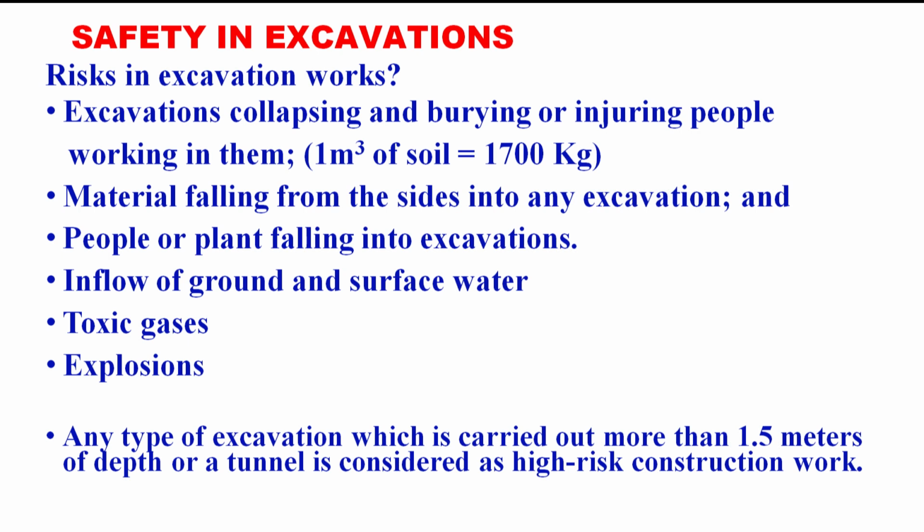Then there may be chances of material falling from the sides into our excavation. If we are excavating, in that channel that has been created after excavation, some material may fall into it. And when the workers are working in that channel or underground work, it may hit those persons. It may cause injury to them, which may even be fatal.